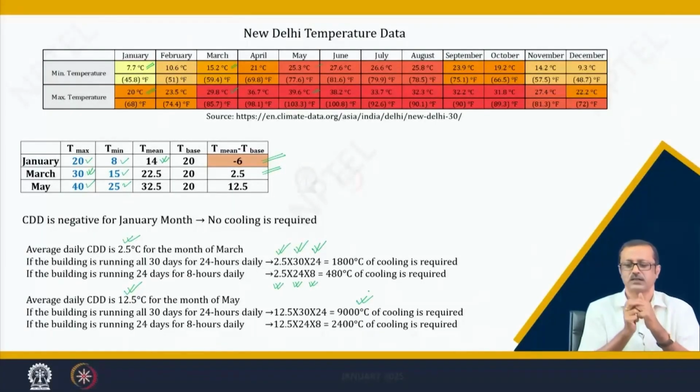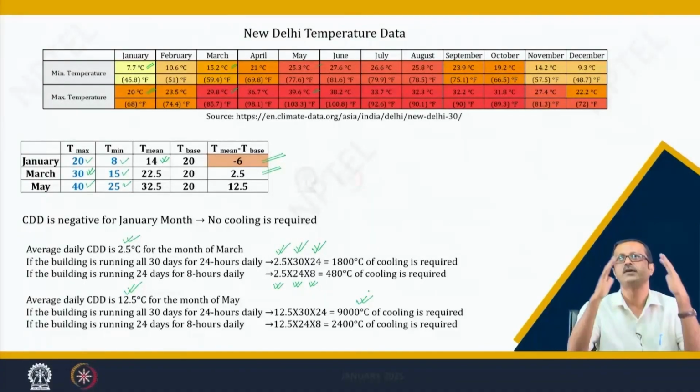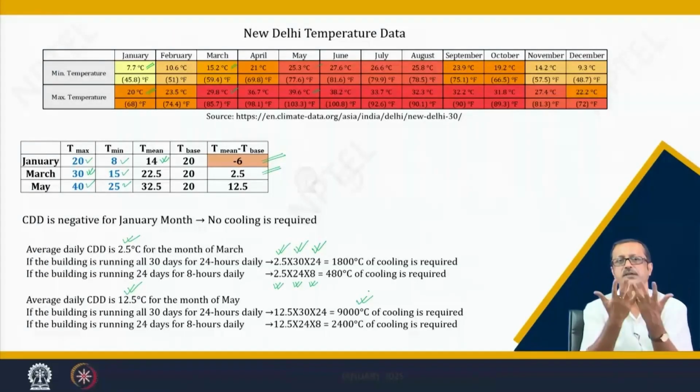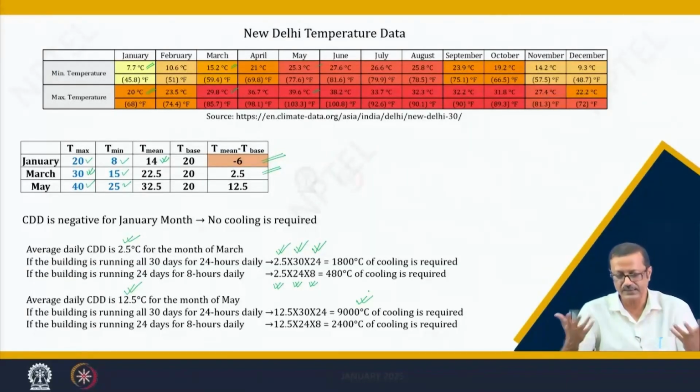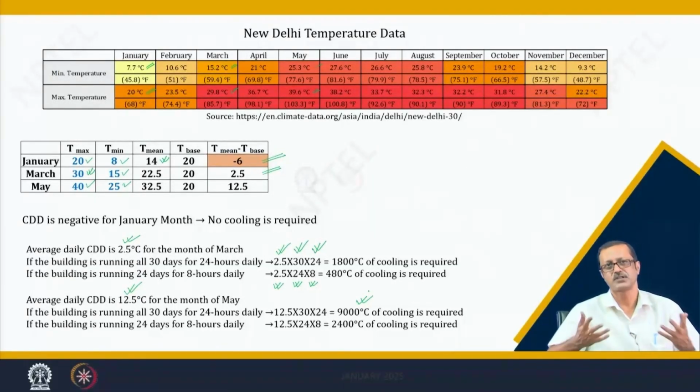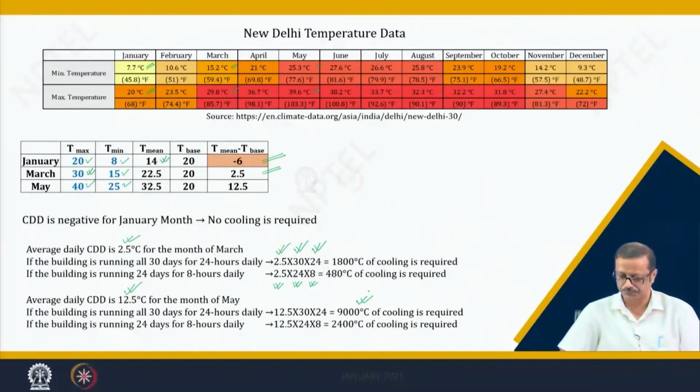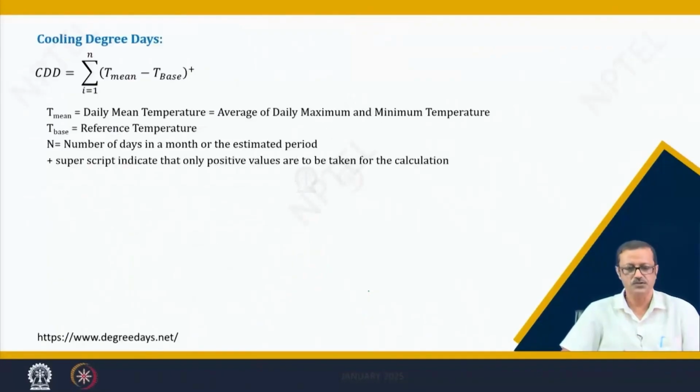that particular month. And now if I multiply with the overall heat gain coefficient, which is the multiplication of the envelope area, corresponding envelope area to the U value, I can directly find out how much is the cooling requirement in kilowatt hour or so.